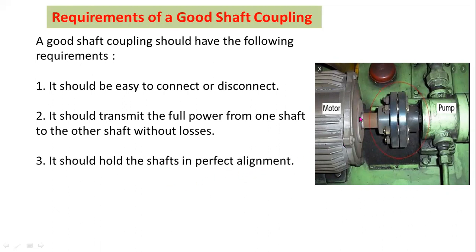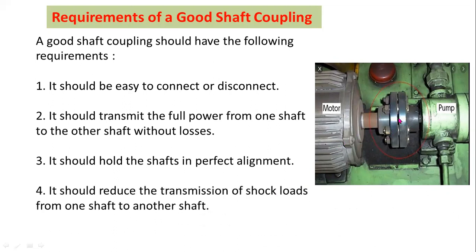Couplings should hold the shafts in perfect alignment. It should reduce the transmission of shock loads from one shaft to another shaft. Couplings should have no projecting parts. So these all are some important requirements of a good shaft coupling.